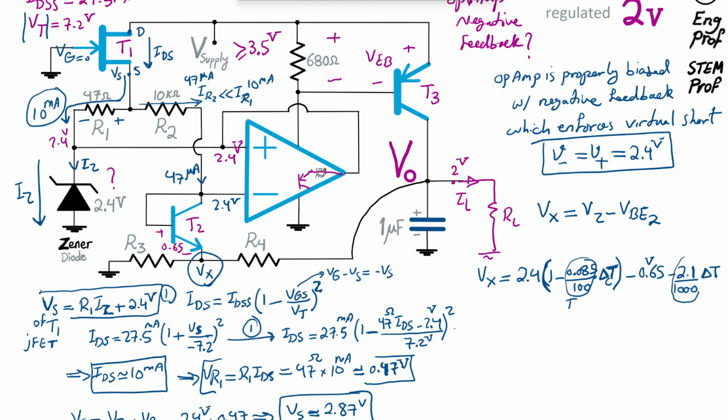So this is our negative 2.1 millivolt, and negative is here. Effectively, what I'm writing here is coming from the temperature coefficient of the bipolar junction transistor. Delta T is simply the deviation of the junction temperature for the PN junction or for the Zener diode, which are thermally connected in this design, from room temperature, roughly 300 degrees Kelvin, which corresponds to about 27 degrees C, but it will be a rough benchmark for the delta T. So what is the meaning of this?